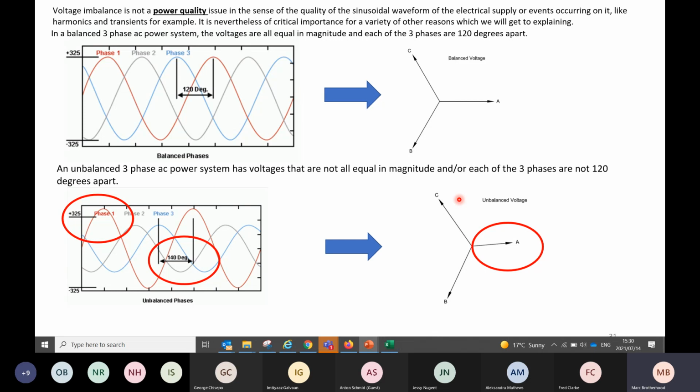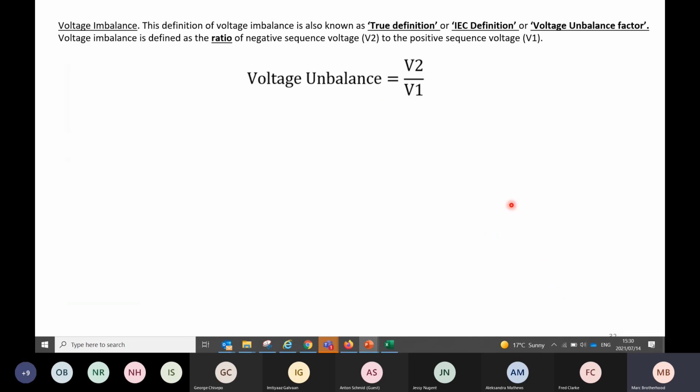Now bear in mind, this is what's happening on my supply. My VRV system, for example, is drawing off of the supply, and I start feeding this unbalanced information and power into my capacitors, which ultimately has a huge effect on my voltage imbalance, which, as you've seen, creates PC boards to blow up. Not over voltage, under voltage is what's causing boards to blow up.